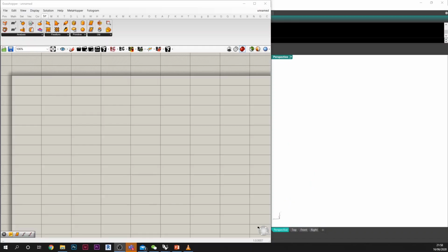So here we go. I suggest that we split in two parts. First part we will do some developable surfaces from scratch, and second part we will analyze them and check if they are really developable. So let's do the first type, which is tangent developable, and build a curve by hand first in Rhinoceros. So you can do a spline curve and make sure that it sits in space, like this for example. Import it in Grasshopper.